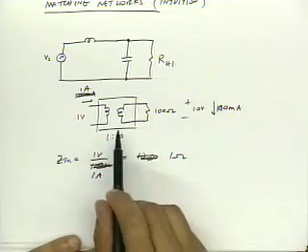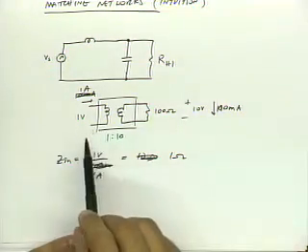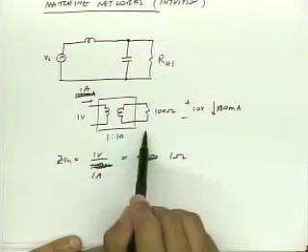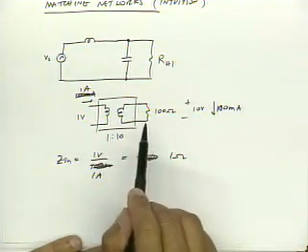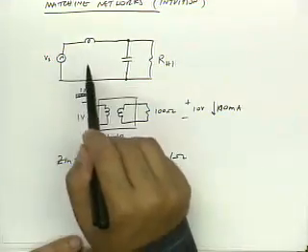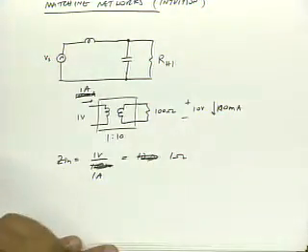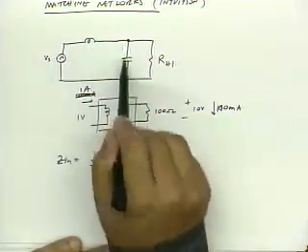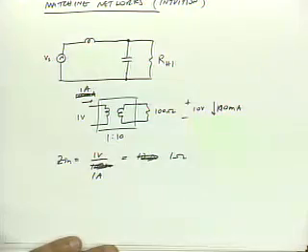So what's happened here in this circuit is the fact that I've multiplied the voltage when I've applied it across here. That did the magic trick. In this circuit, if I can think of this as a series feedback circuit, then I can also produce voltage multiplication across a reactance, right?